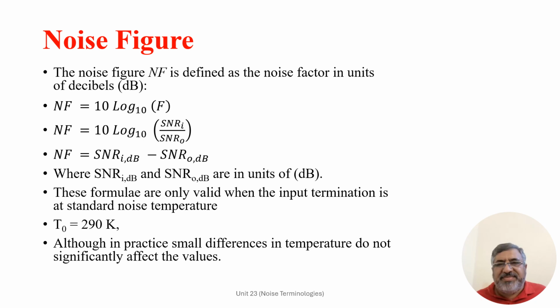Noise figure is the measure of the degradation of signal to noise ratio caused by the device or system. It is generally expressed in decibels and represents the ratio of signal to noise ratio at the input to the signal to noise ratio at the output of the device or the system.